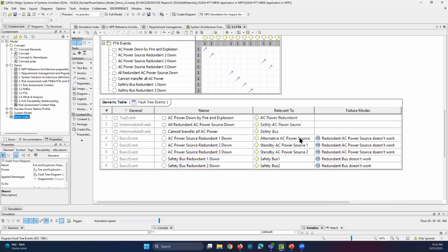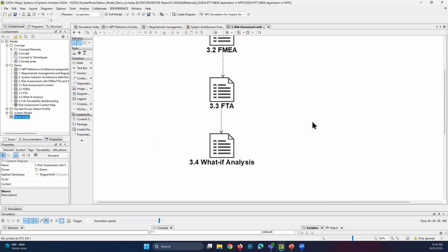So then we are able to use it to correspond complements into the failure mode, and then use the simulation to calculate the probability and actually compare it with the occurrence in the FMEA tool. So both of them will complement each other, and using the models, we have a lot of opportunity to automate them, right, to make it more effective.